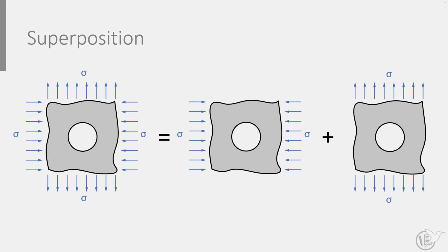The opposite is also true. If the vertical load is tensile and the horizontal load is compressive, but equal in magnitude, the peak stress goes up to 4. This means that the stress concentration for biaxial loading may vary between 2 and 4, dependent on the combination of the load.